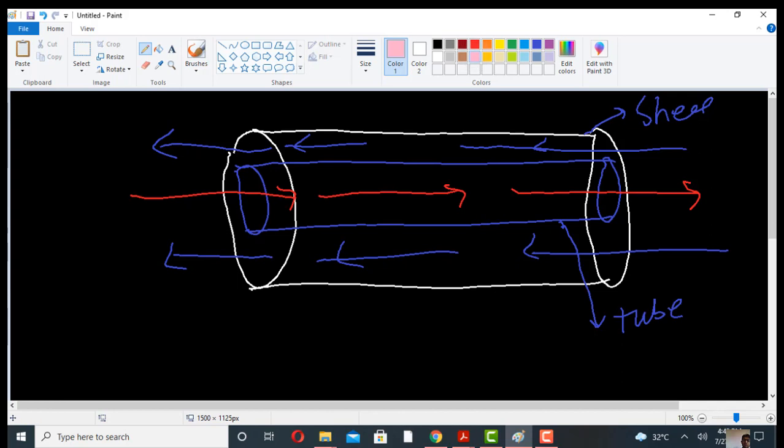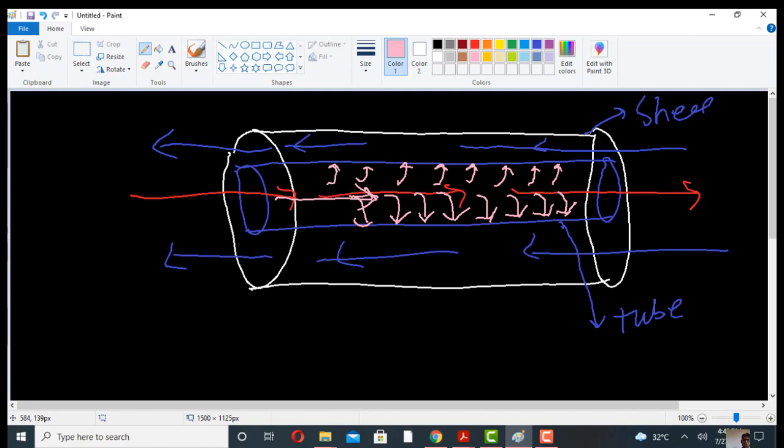So in this case, there are resistances to the heat transport. Suppose the hot fluid is flowing through the tube. First of all, the resistance to the heat transfer will be offered by the hot fluid which is flowing in the tube. Similarly, there will be another resistance to the heat transfer, provided by the thickness of the tube wall.